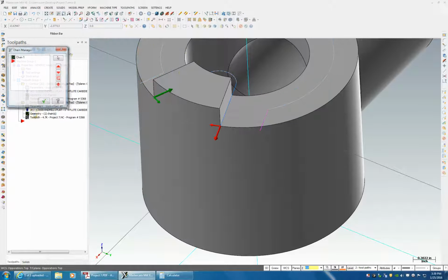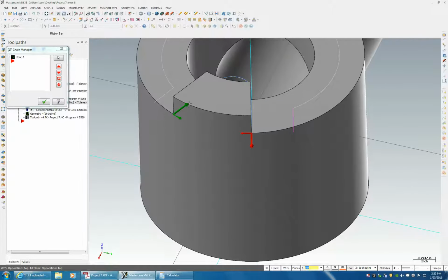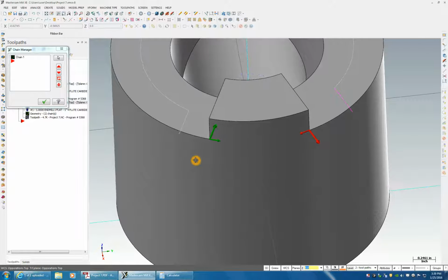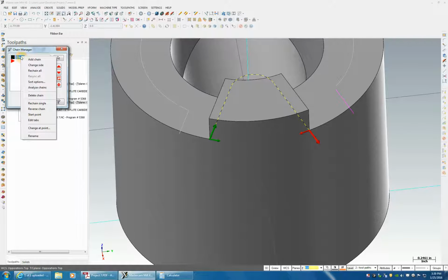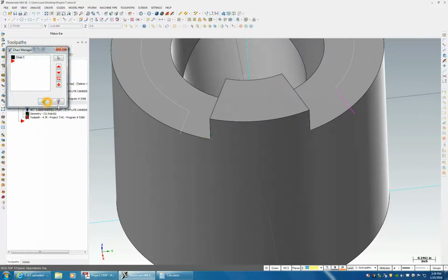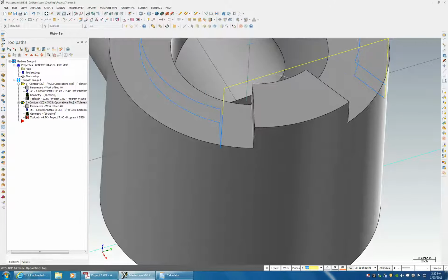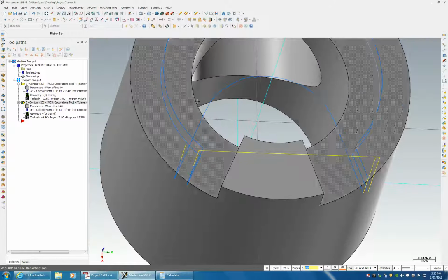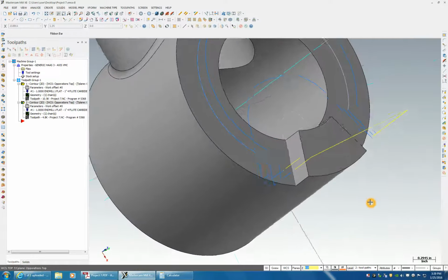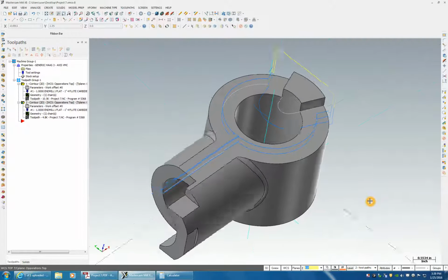Easy to fix. Open up our geometry. Green arrow, big arrow indicates the direction of cut. Little green arrow means side of cutter compensation. So all we got to do is come here and change sides, and that's what we want. It's going in the right direction. Reproof, and now you see this big arch. So let's simulate and see what we get.